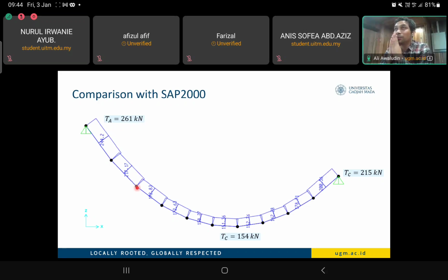But please consider that the fracture of this system is sudden. Once it reaches the yield strength, it suddenly propagates and suddenly collapses. Just to understand this one. So it is a very efficient structure, but when it comes to collapse, it becomes very brittle. That's my understanding. Afif, does that answer your question? Yes, doctor. Thank you.